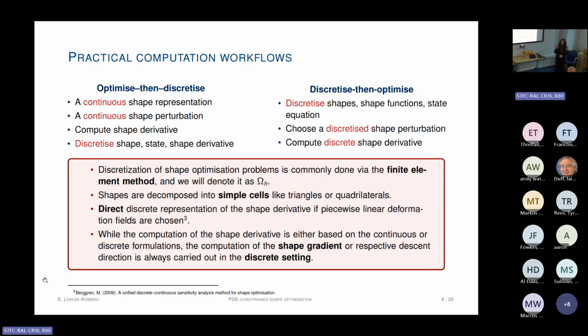I think at least that the main problem about initializing a new mesh every single iteration is, of course, that when you have real big problems, initializing or getting a new mesh at each time is very computationally expensive. You need to save a lot of information. And something that, at least in my aspect, is very important is the fact that when you change your mesh, you lose this continuity of your objective function, which at the end you would like to have, for example, to have convergence of algorithms, or just simply to understand how you are decreasing the value of your objective function.